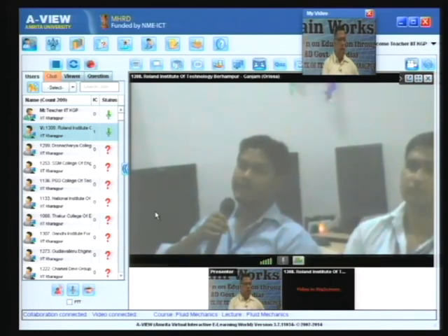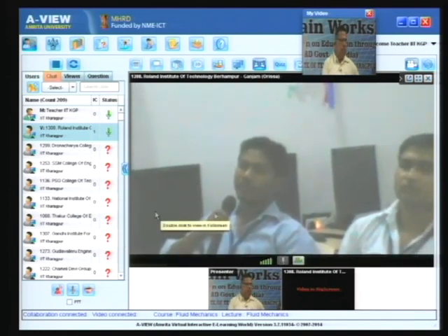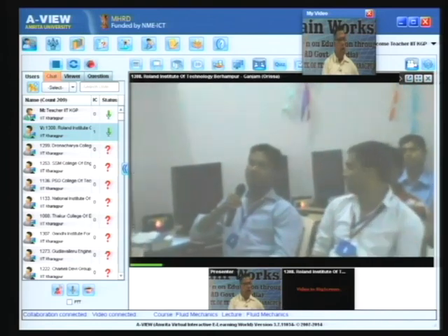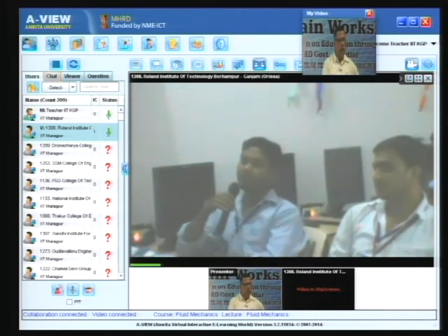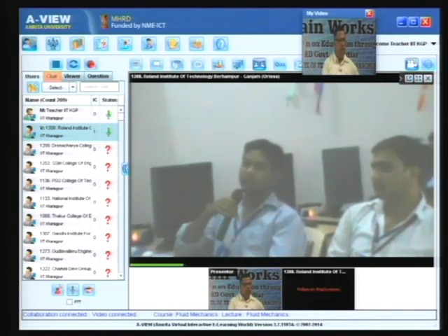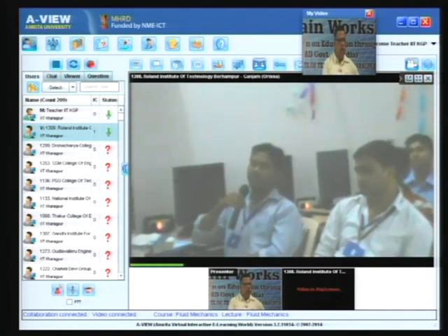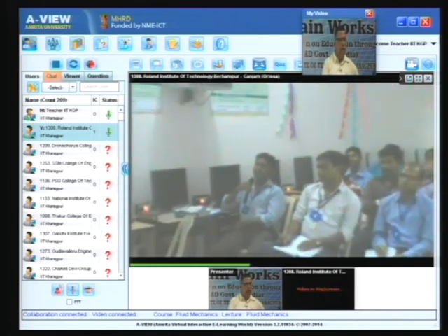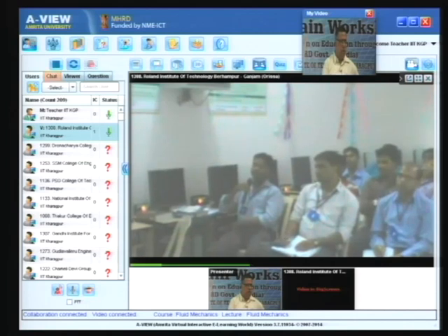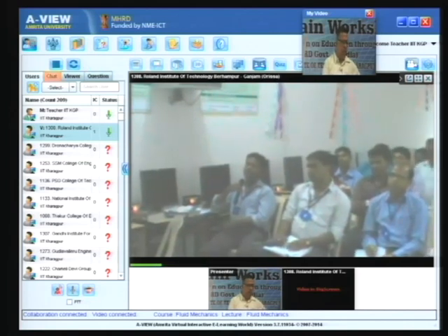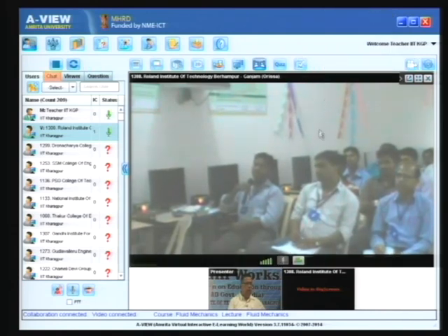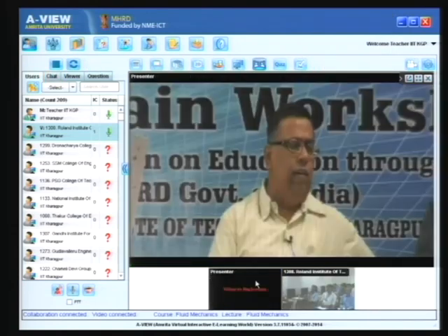See, I do not understand your notation. I did not use the notation which you are talking about. See, in my derivation I had kept the origin at the centroid of the immersed inclined plane, and we found that the center of pressure is below. I gave you a physical explanation: below the centroid of the plane, the reason being that the pressure is increasing with depth.